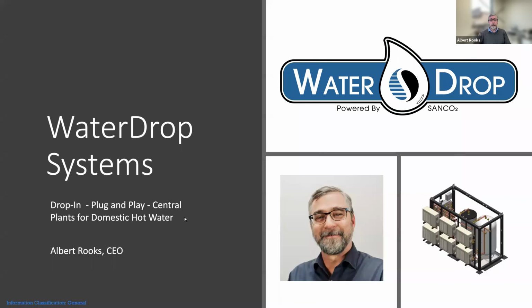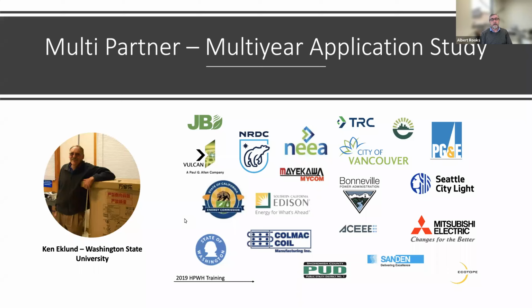Design for how we design central heat pump plants, mostly we'll be talking about CO2 today, and apply those into multifamily buildings. Multifamily building is really the model that we'll be talking about today. Of course, there's other building types. They have different load characteristics, so we'll stay on multifamily buildings right now, or at least residential.